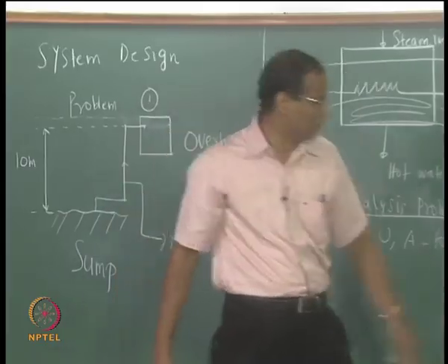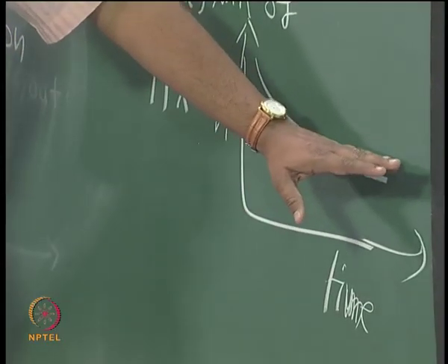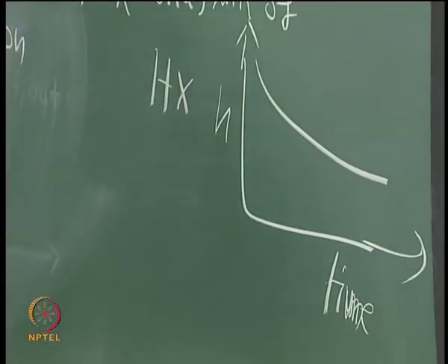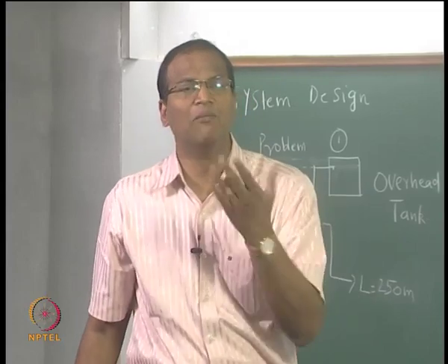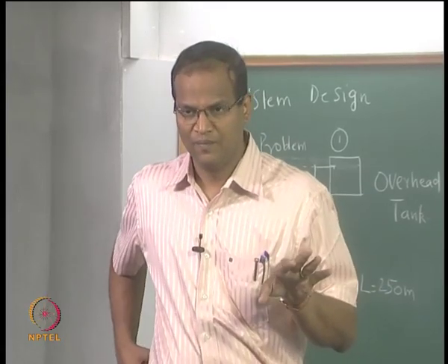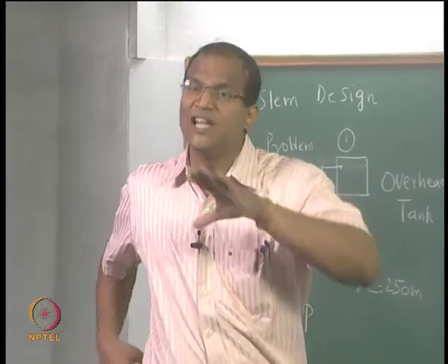Suppose you want to design it for 15 years, you have to consider all this. There may be something like what is known as an asymptotic fouling factor. Eventually it will settle down to a fouling factor that can be obtained by doing calculations and so on. Are you getting this point? So design will involve all this.